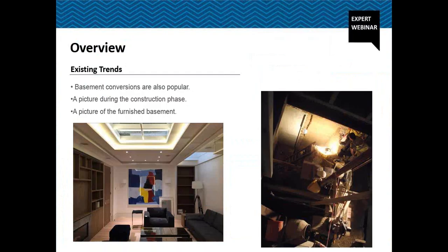Here you can see the reinforced concrete underpins being installed in 1 meter sections, supporting the existing building above. You can also see the reinforcement bars sticking out to be connected to the next underpin. And over here you can see the finished and furnished basement. However, due to labour costs and the laws involved with underpinning shared walls in adjoining properties, construction costs are relatively higher than those associated with above-ground extensions.